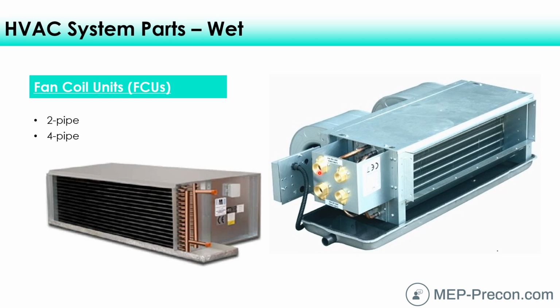We will have some system videos that get into the pros and cons of different types of systems. But for a hotel, a four-pipe fan coil is very quiet. You don't hear any compressors. And so high-end hotels anyway would have a four-pipe fan coil system, and that gives you the means of providing heat or cooling, whatever the thermostat calls for, year-round.